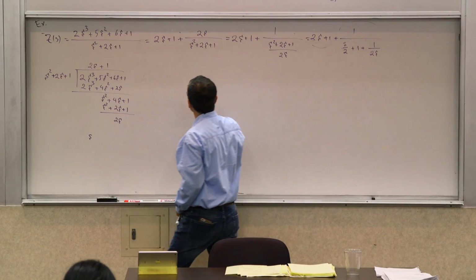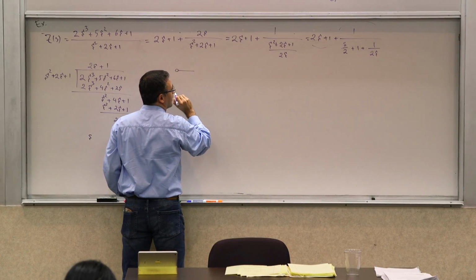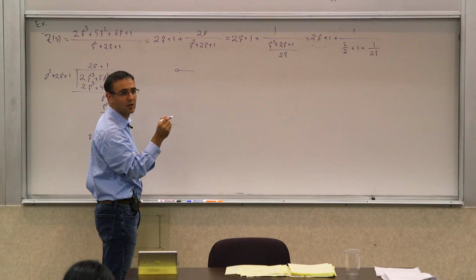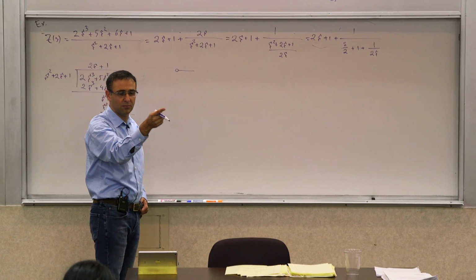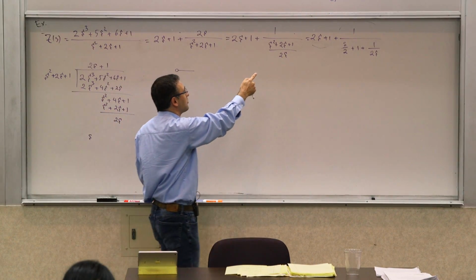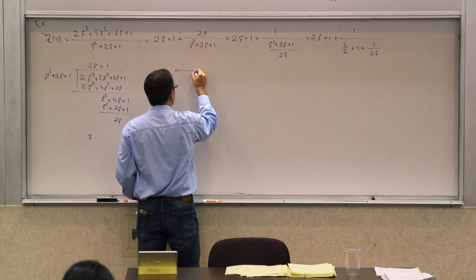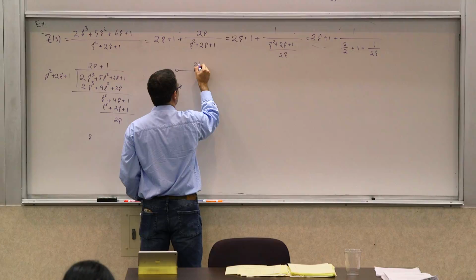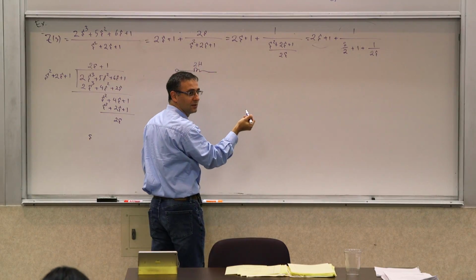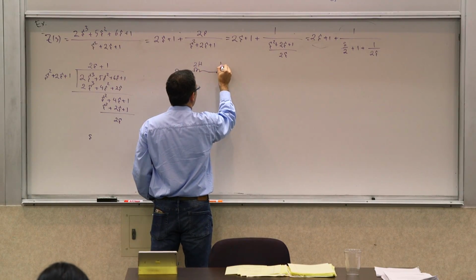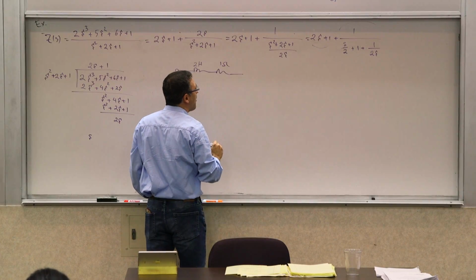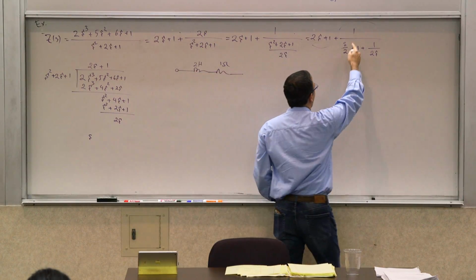So that first impedance, I can write it as what? What is the first impedance? It's an inductor plus, you can look at it individually, right? What is this impedance? It's an inductor of value 2 Henry. And what is the next one? A resistor of value 1 ohm. And now you're adding it to 1 over something.